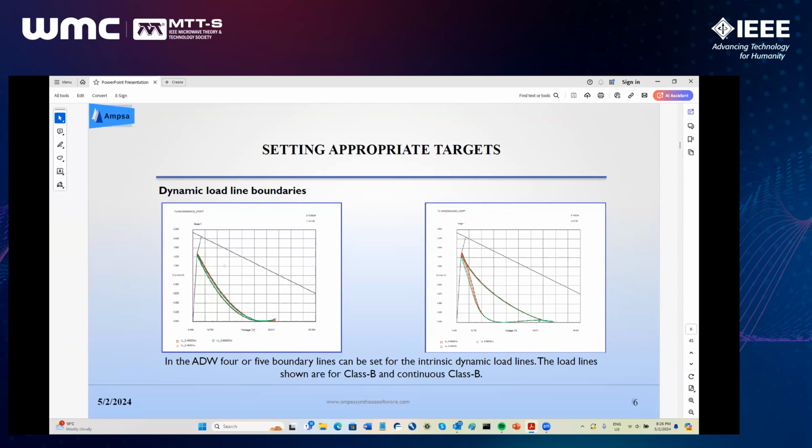So this is the class B load line. Now, interesting, we have heard about continuous modes. You can see these things are wrapped in tightly, so they're resistive. But this one is open. So this is a continuous class operation. Now look at the voltages. This is class B. The current is more or less the same, the peak current, but the voltage has increased quite a lot. So this voltage stopped here, but that one stops quite a bit further. So that is a question again, can your device handle the bigger voltage? If it can, good. If not, then continuous mode is not for you.